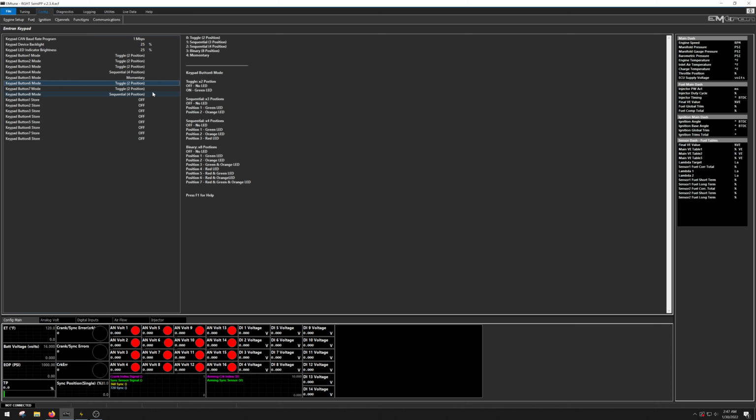I have blip shift enable, so it's going to crack open the throttle blade on the drive-by-wire on downshifts as estimation for downshift on number 7. And then I've got what I have labeled as drink mode, which is flame control, drinking my fuel. So I've got a picture of one of the Emtron printouts for the keypad, a picture of like a cocktail being made. It's awesome. So that's number 8.